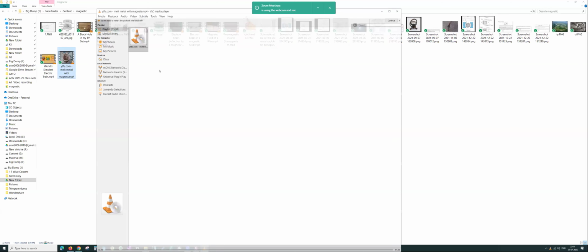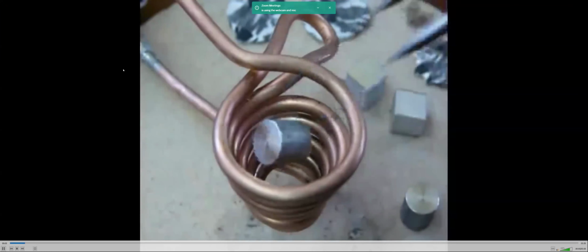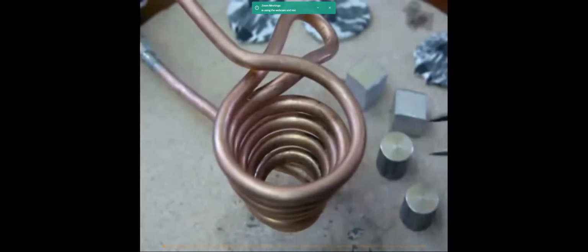Anyway, look at this thing. This is actually, if you see, kind of like a solenoid. You can see the coil there. So you're sending a huge amount of current there and you're putting a metal piece there. There's like a magnet there, so it's repelling. Can you see how it is floating in the middle? So if you leave it like this for some time, there's something called eddy currents. We will see that in the next chapter.